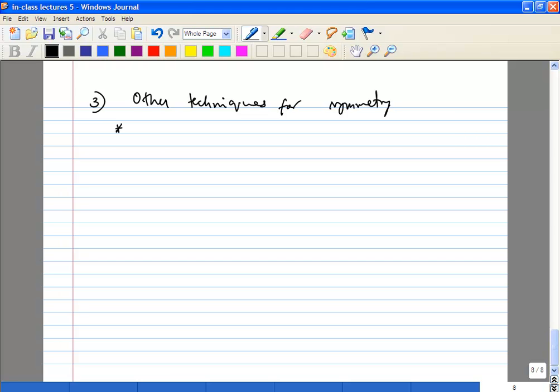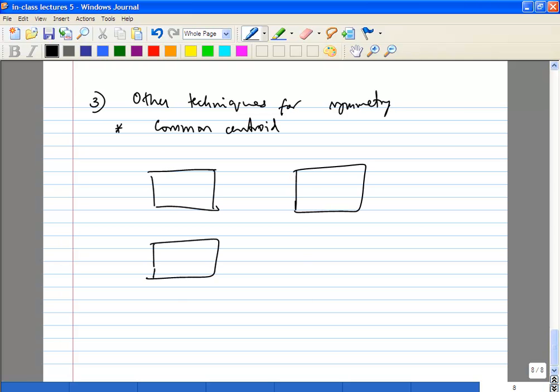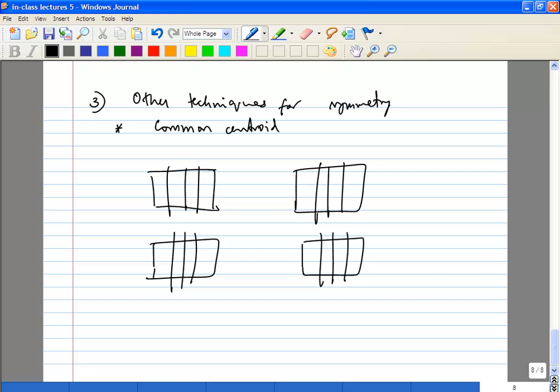So you can do what is called common centroid, which is where you split the transistor, and you can combine all of these things. For example, you split it into 4 sections and each one of these can be interdigitated. So this common centroid can be used in conjunction with the previous technique.